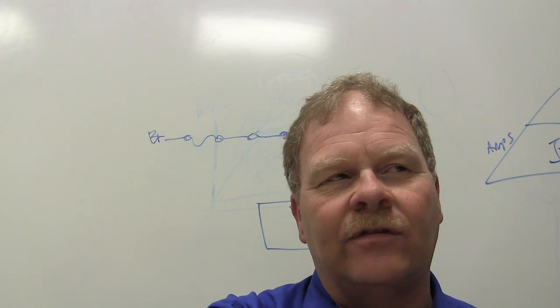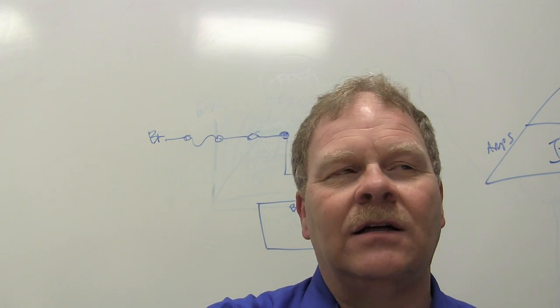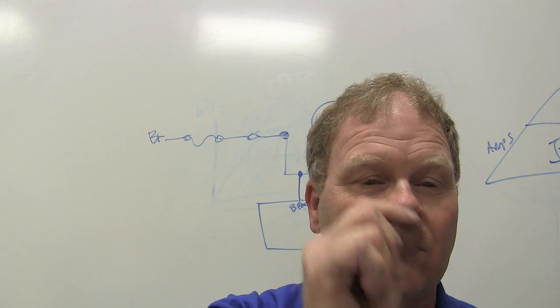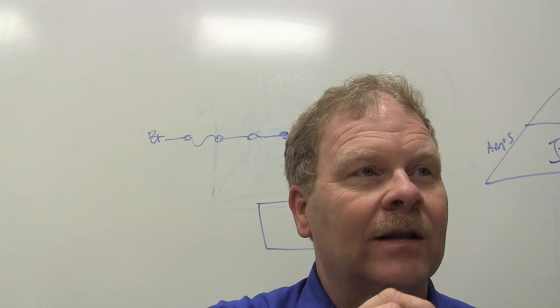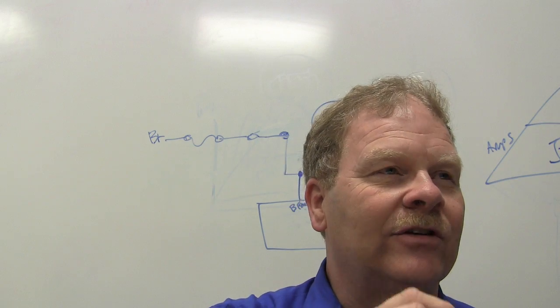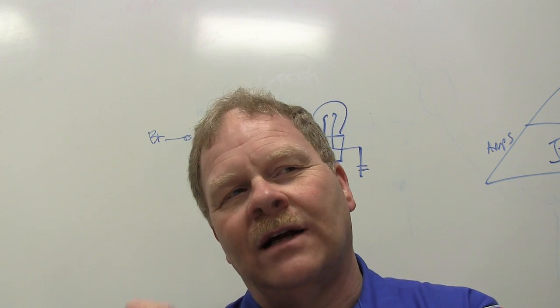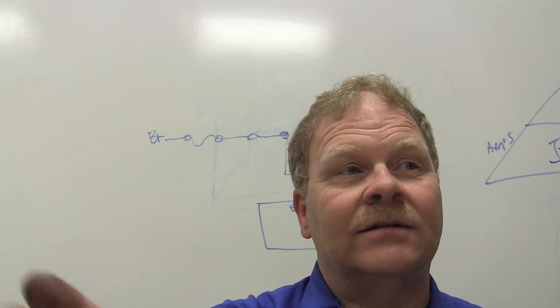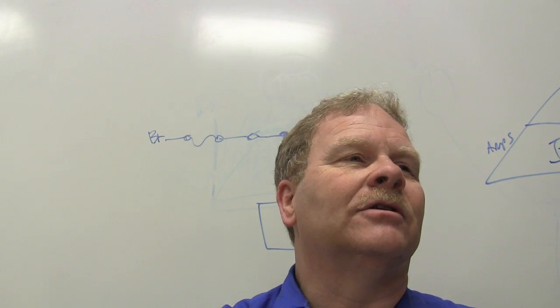And I said, now there's another Focus over here just like this one. And so we back probed that one with a little straight pin, and we touched that one and it was bright. I said, what's the difference between these two? The one that the cruise don't work on has got a dim light. The one it does work on has got a bright light where the brake feed goes into the cruise module.